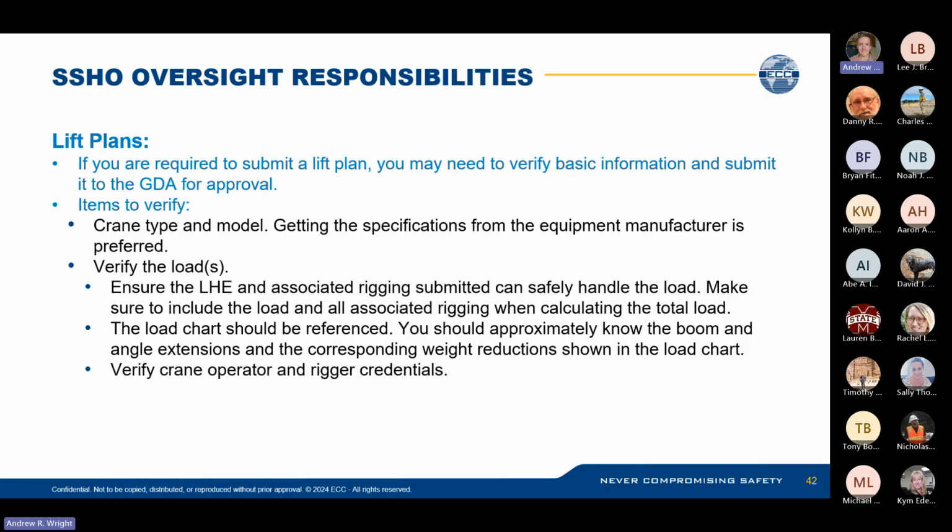And lastly, you want to make sure the crane and rigging credentials are up to par. They do have expiration dates on some of these certs, so make sure that they're not expired, and make sure that the guy who shows up is the one that was submitted.